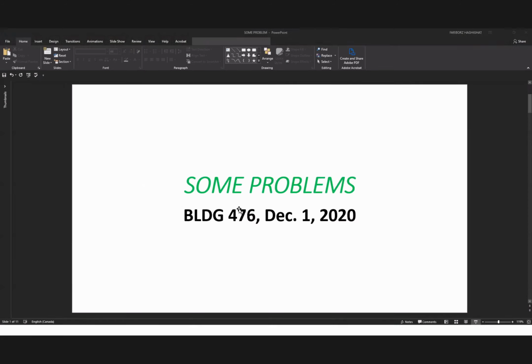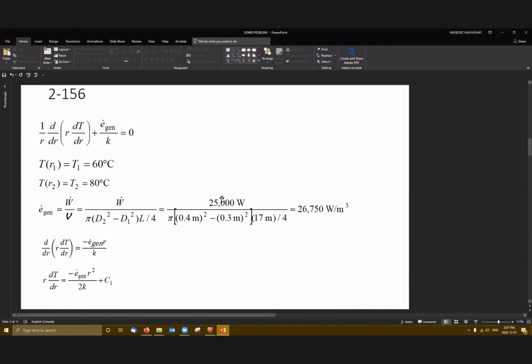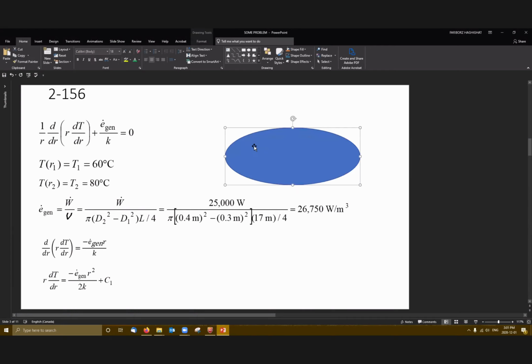Okay, let me see if I can get the figure here. This is a cylinder, but it has a thickness. The inside boundary is mentioned at R equal 15, so this is the inside diameter. The inside is exposed to fluid passing through at 60 degrees, and the outside of the pipe is exposed to the indoor environment at 80 degrees. Therefore, there is no symmetry here.